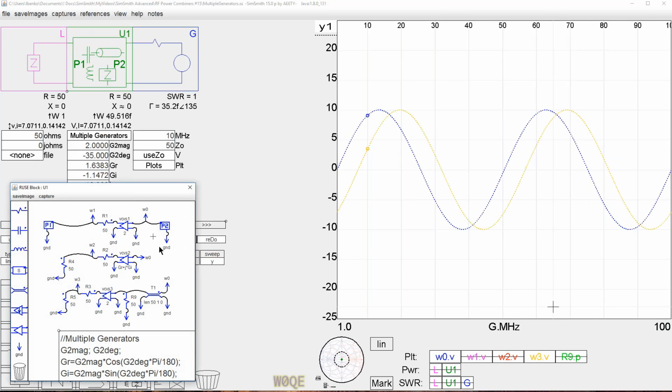This circuit, I've got three voltage controlled voltage sources now. And if we look at this, there's no resistor here because this one down at the bottom has created a delay with a piece of transmission line. Ignore that for a minute, but this 50 ohms gets transferred across to here, and there's 50 ohms right here.